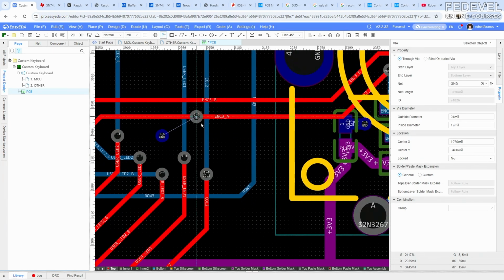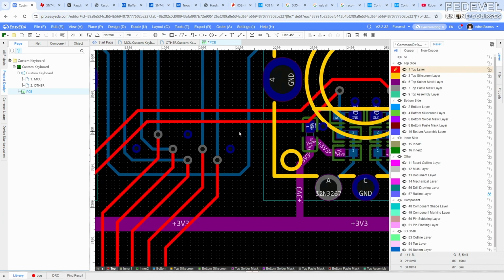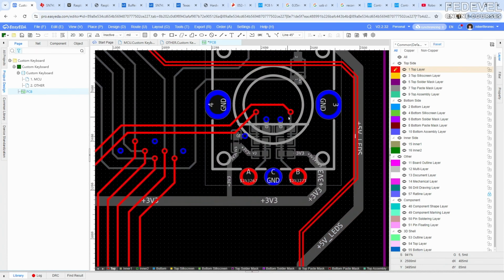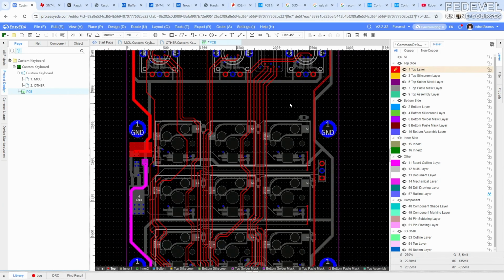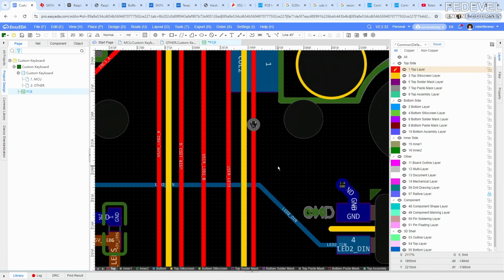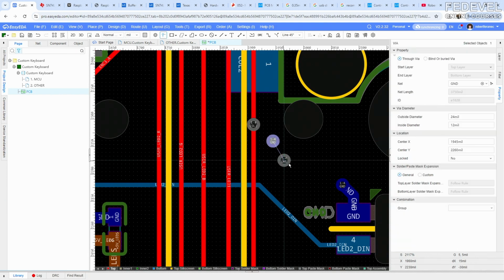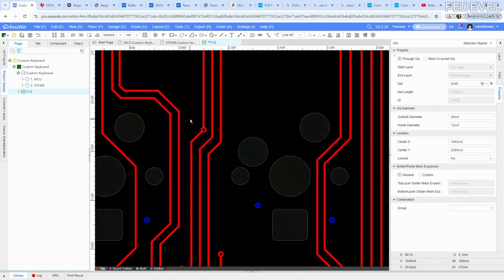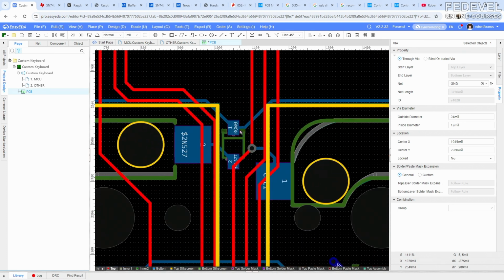So even when we are designing this very simple board, it's good to create this habit and use it even on simple boards. And especially we have a lot of free space here, so there are already some vias, so we can place these extra vias on our PCB. We can place one here. In case there are already some vias, because there are, I don't know, decoupling capacitors or something, you don't need to place them there, okay?